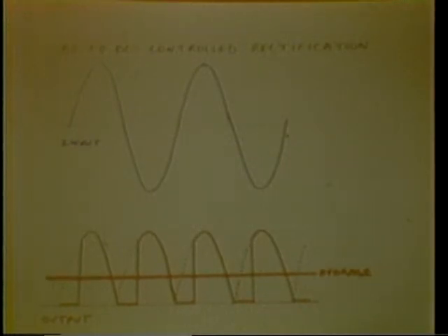Other examples of waveform processing that we can do, this is a simple phase control rectifier, the kind that you have in your wall switch that dims the lights. In larger sizes, this is used on the New York-Washington Metroliner train also.